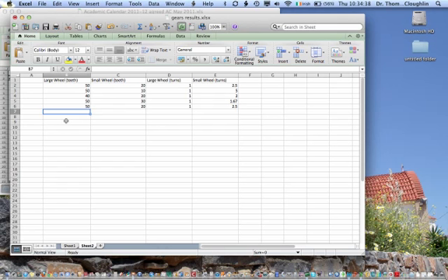So if 2 to 1 is the ratio of the teeth, then 1 to 2 is the ratio of the turns. It's turned about. Because the first thing in the ratio refers to a particular wheel, and the second thing refers to another wheel.